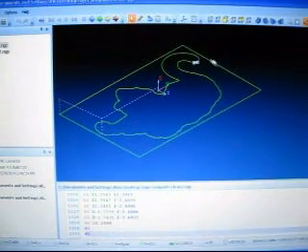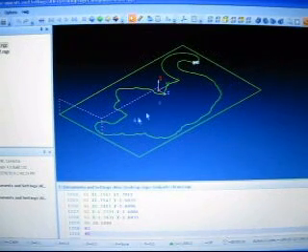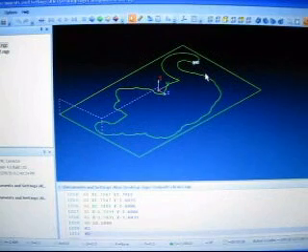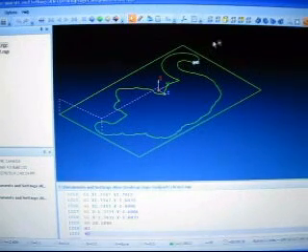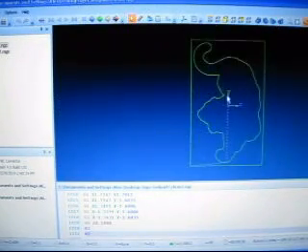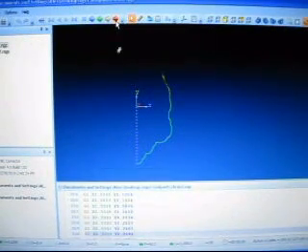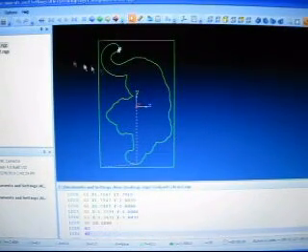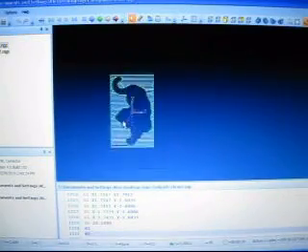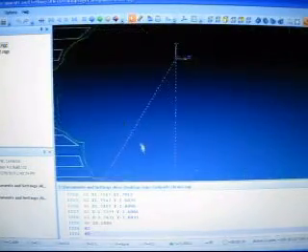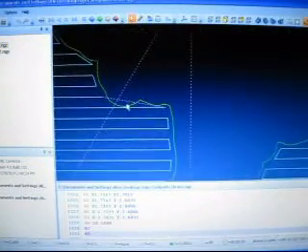So this is going to show us our outline with the tool offset for a 1/4 inch tool, which is 1/8 of an inch, plus the 1/10,000th of an inch. Don't forget about that. All right. So basically, that's the tool path, how it's going to run. So I'm going to overlay this onto it, and here is the rapid motion in question.